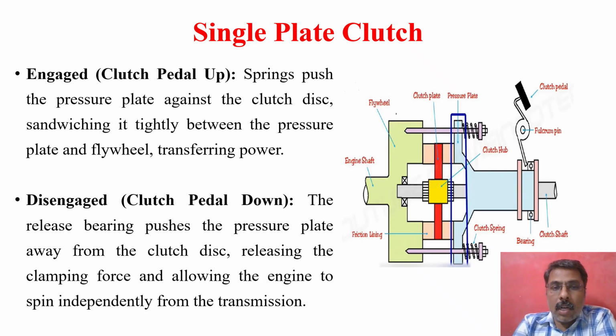When the driver presses the clutch pedal, the spring releases its pressure, or tension force, over the frictional plate surfaces. Then the friction plate moves in this direction, which releases the external force of the spring.